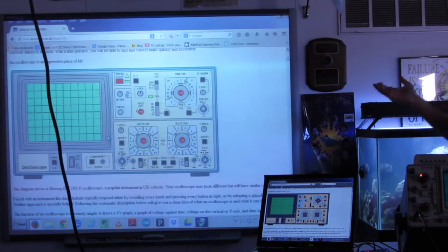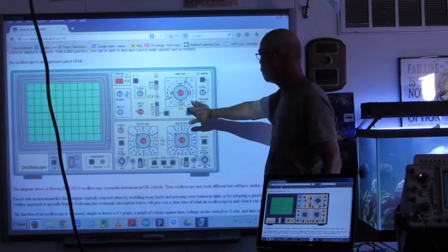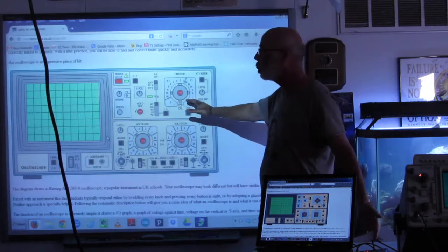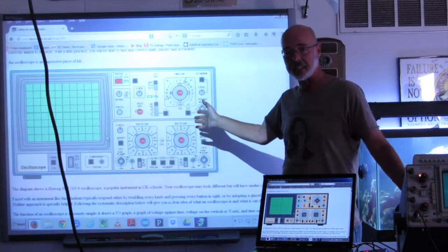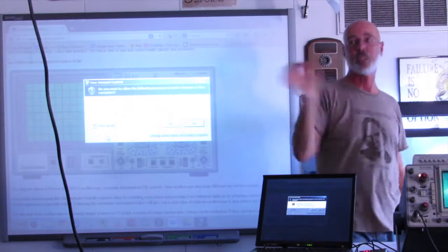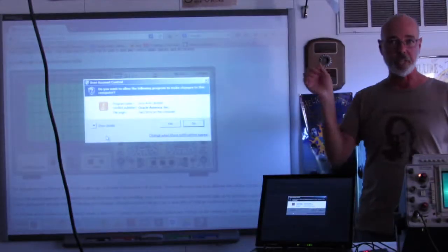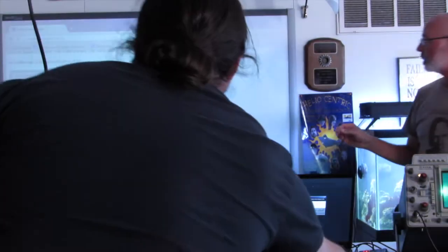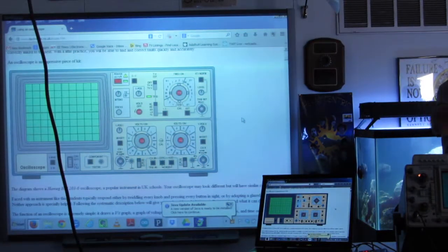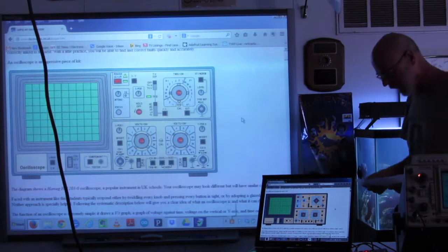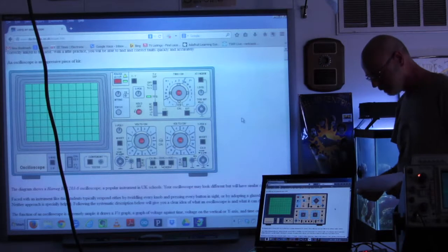all the way up to, most scopes can go up to about, typically, 20 nanoseconds, 20 billionths of a second per division. Okay. Now, that's really fast, okay? You can look at radio signals with a speed like that. And that literally, on an analog scope, means that beam is sweeping across the screen in 20 billionths of a second if you have the horizontal sweep set that way. Okay, so enough about the horizontal channel.